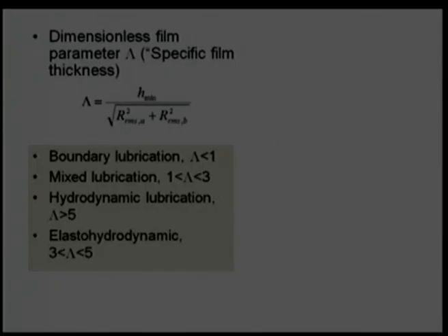In that case this is hydrodynamic lubrication. There will not be any contact, and the life of the interacting surfaces will be infinite. There will not be any wear, there will be only friction, and we say that because of wear, a component has a restricted life.